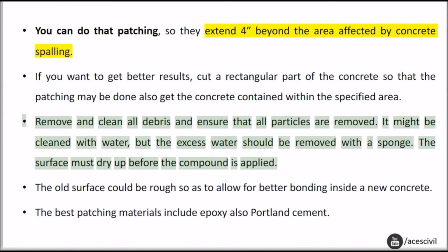Remove and clean all debris and ensure that all particles are removed. It might be cleaned with water, but the excess water should be removed with a sponge. The surface must dry before the compound is applied.